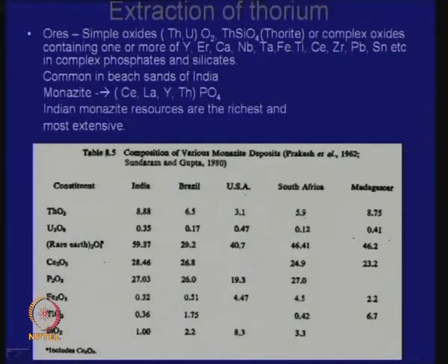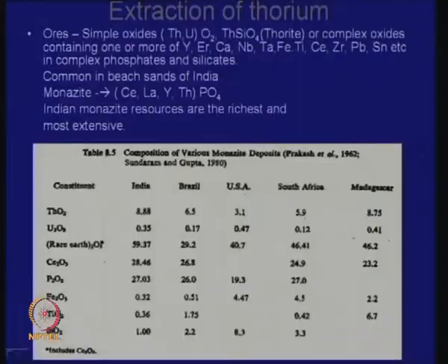We are looking at ilmenite. Ilmenite is FeO-TiO2, we take out ilmenite, then produce artificial rutile, means remove FeO and produce TiO2. But then the rest are not to be wasted, that is where we have monazite, we have rare earths, we have many other things. So, it will all be coming from beach sands, and I mentioned some of these beach sands look black because of the very high TiO2 content. So, this TiO2 that is being shown in this table is only the TiO2 that is associated with monazite fraction.